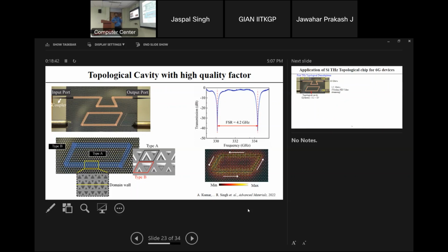And if the wave comes from this waveguide, then these dips represent the resonance frequency, which is measured here. So these two dips are the whispering gallery resonance frequencies. If you have seen, 2πn equals n times the length of the whispering gallery resonator. So if we increase the size, then the number of frequencies will also increase. So for this device, we chose the length such that we have only 2 frequencies. We don't want multiple frequencies.